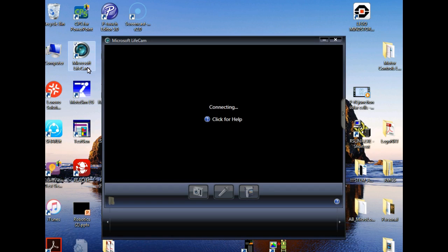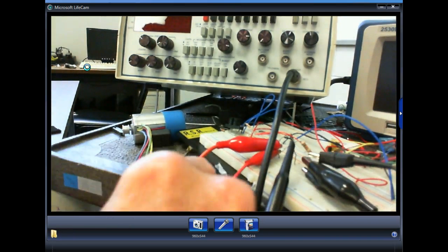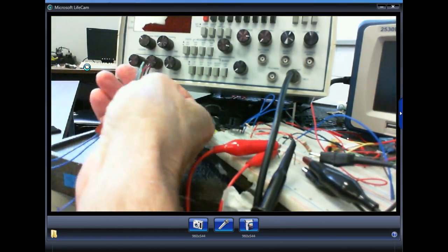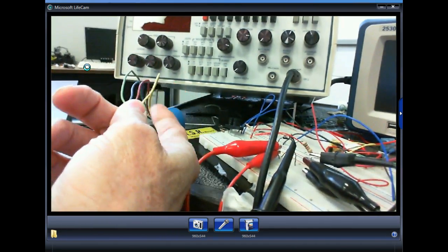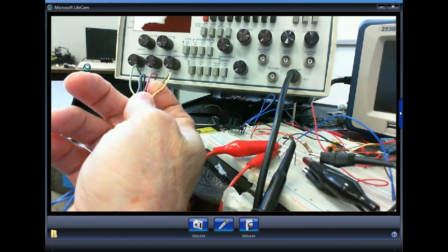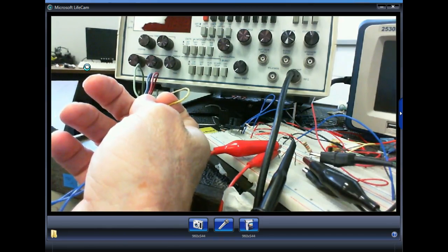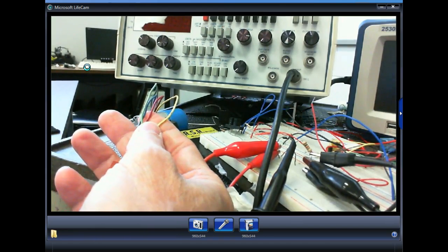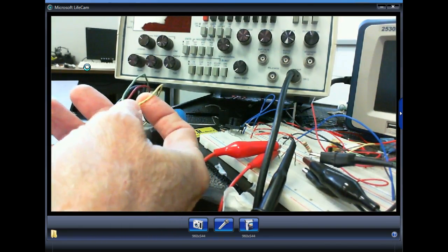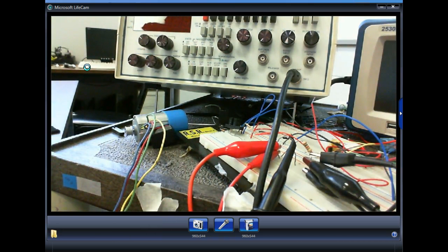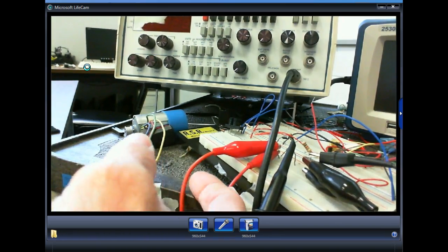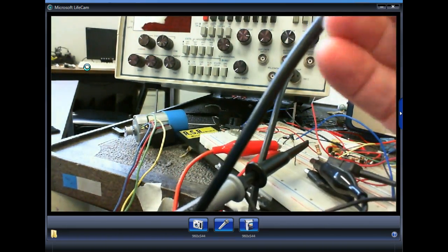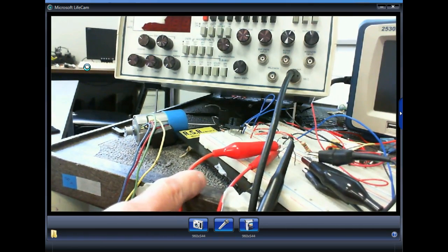So these are conductors coming out of this little DC motor. And of course here, the insulator and the jacket are the same. So here the insulator is actually what's protecting. Not only is it keeping the voltage inside the conductor, it's also what? It's also protecting us against the environment that little thing was designed to run in, which is not very friendly. These guys right here, this is a cable, by the way. So here's the jacket, and then here are the two conductors.